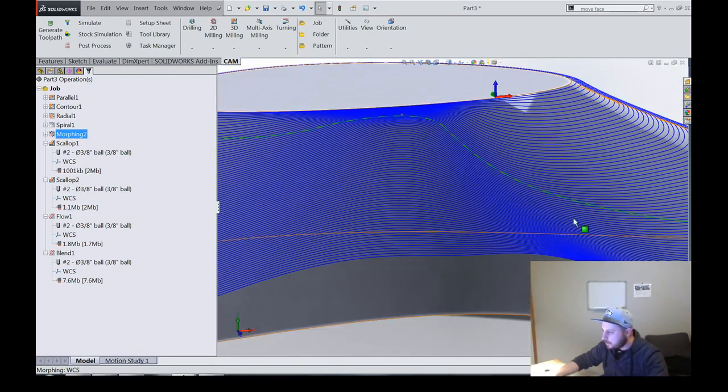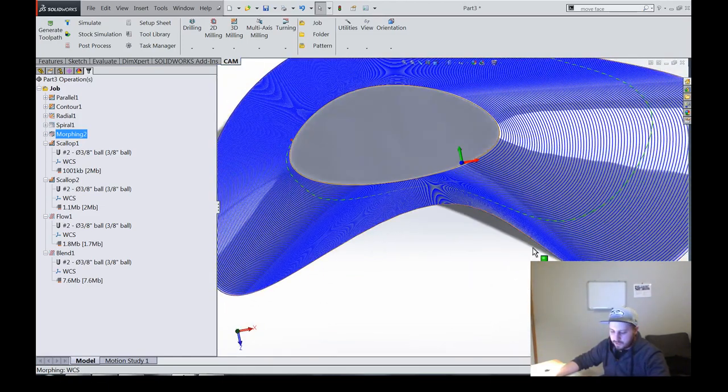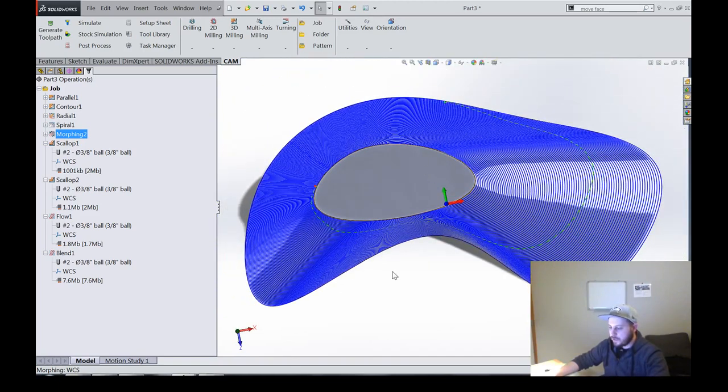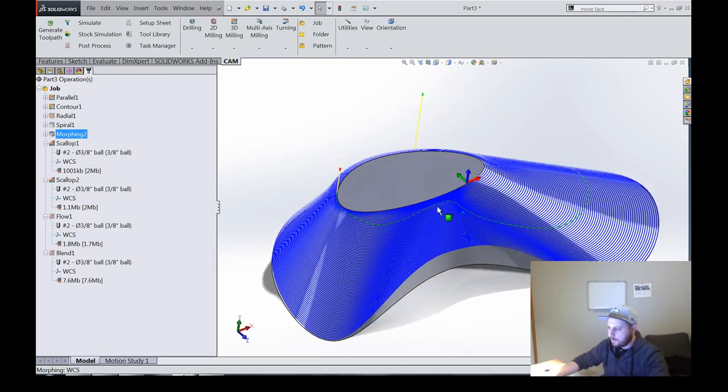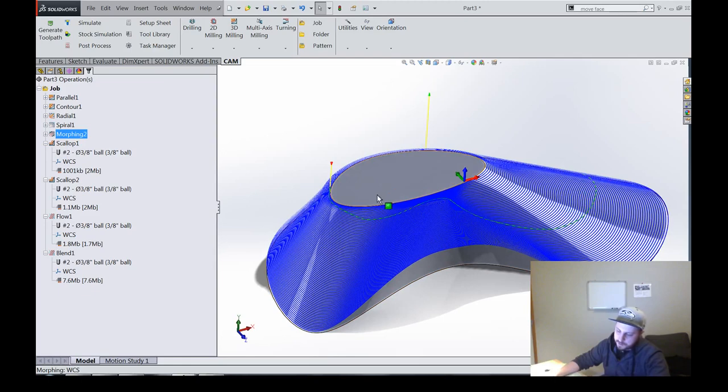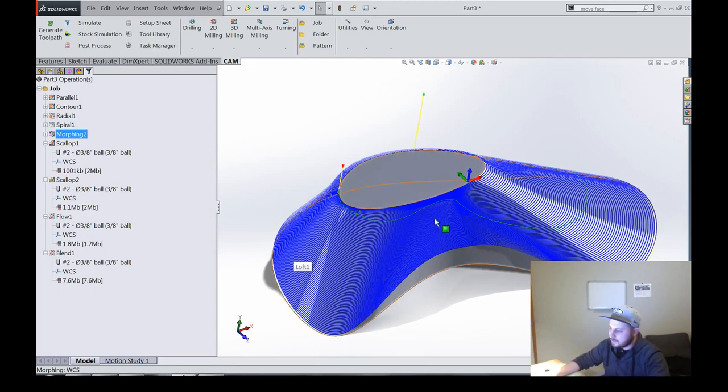We're actually starting to get a little bit of a collapse in here. You can tell that's why it's tighter in through this section. But it usually tends to fail the efficient test. It's just because if you're morphing from here to here, this is a huge area, and it's really the surface difference, and so this isn't that big, but the distance between here and there is quite large, and so with an equal number of steps, and it has to maintain an equal number of steps, even if you're driving it with a step over size, it just winds up with a big difference.